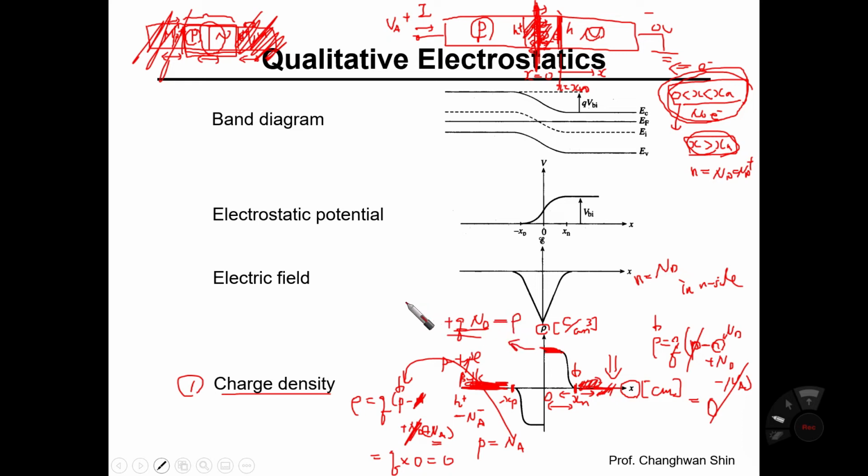Why is that? Again, go back to the generalized equation for charge density, Q times p minus n plus Nd minus Na. In this depleted area, there are no holes and no acceptors. We are in the N side, so there are many donors, but no electrons, because this is the depletion region. This region is depleted of electrons, so n is 0.